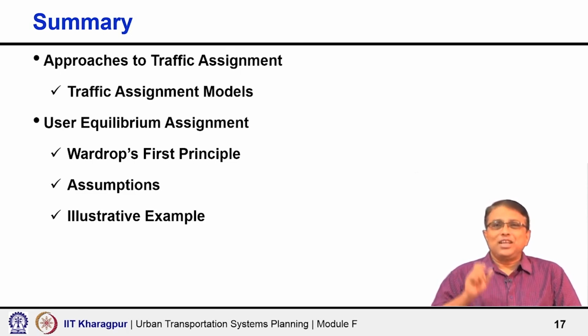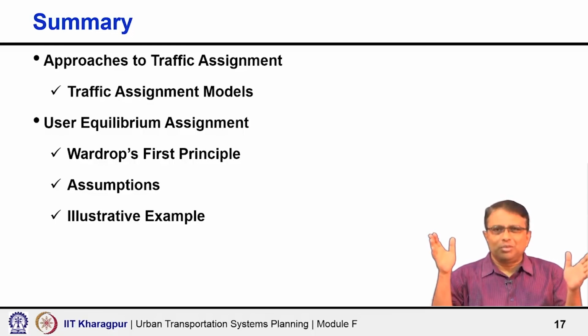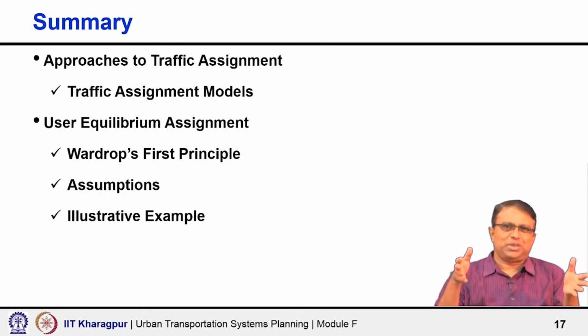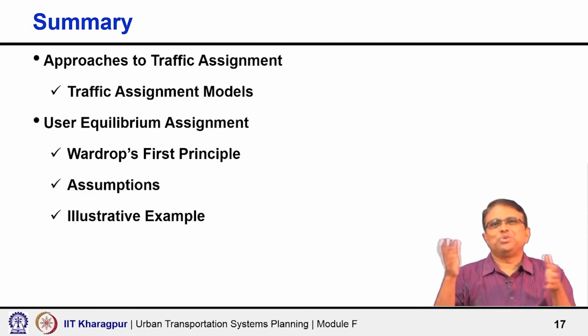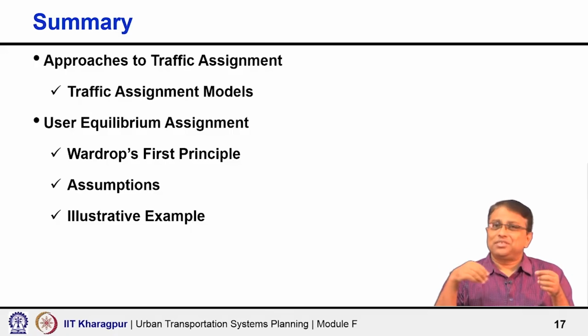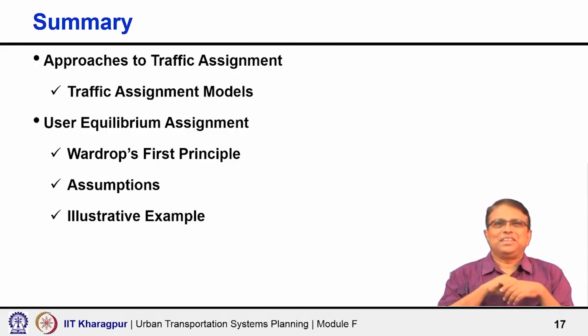One, that time is taken as the demand is time variant, and in static assignment we are taking over a longer period of time, overall demand, what is the average thing that is expected. When you go to dynamic assignment, you will see that we consider every time interval how the things are getting linked.